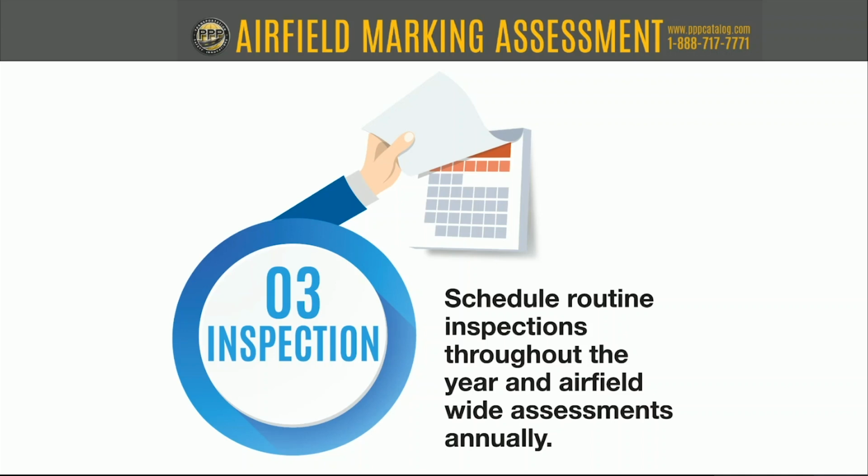I think for most airports, and I'm talking about maybe the top 200 as far as size is concerned, annual is probably a good idea. Really, the busier you get, if you want to see trend analysis, maybe increase that to biannual assessments, airfield-wide assessments. And the smaller you get, probably the more you can stretch these out, instead of annual assessments, doing them every 2 years. I think it's a pretty good schedule.